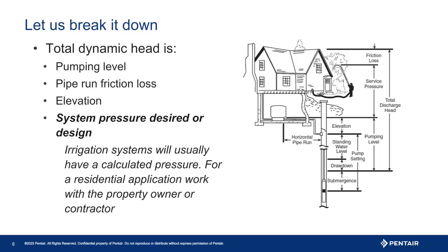Now that being said, does a variable speed drive work on that big a pressure swing? Typically, not, and wanting to sell a variable speed drive, I would calculate the high pressure desired. Again, converting to feet of head.